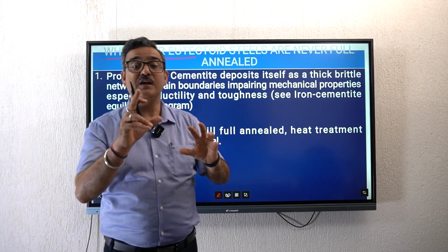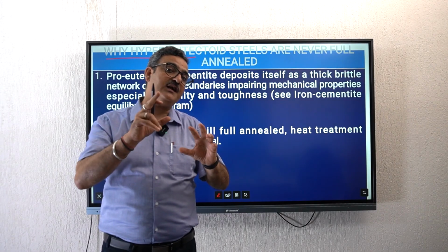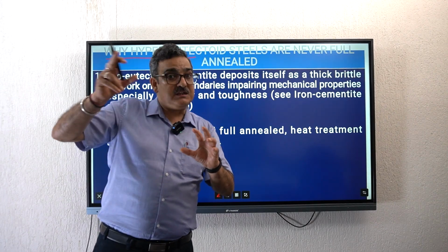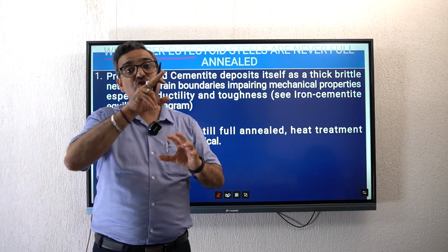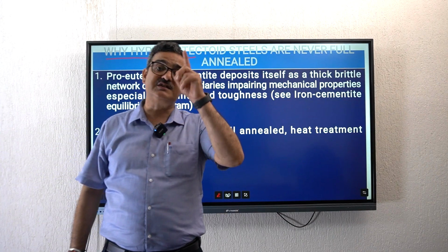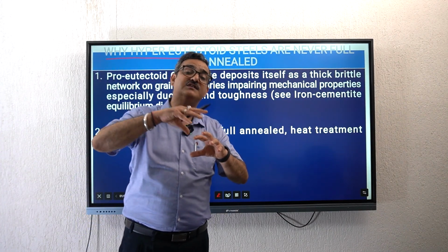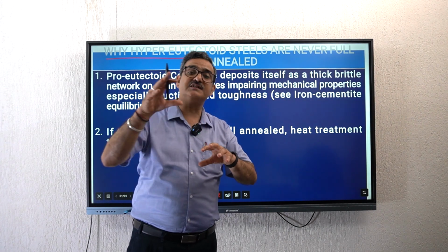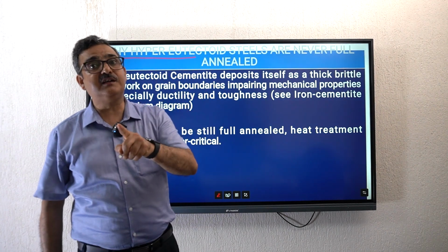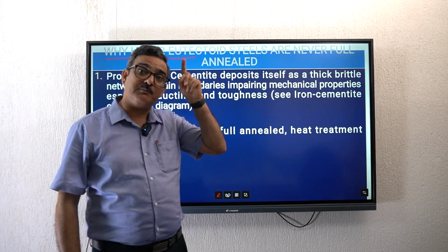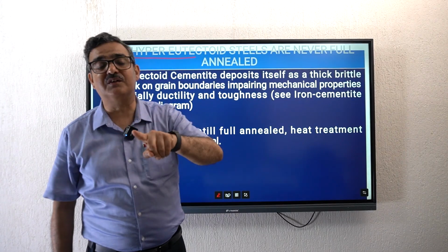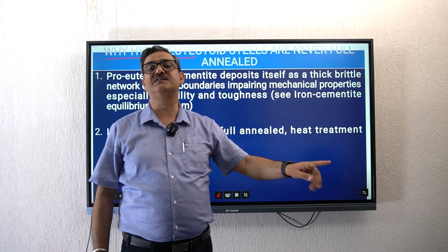But what did I tell you? If pro-eutectoid cementite happens to precipitate in any steel under slow cooling conditions, which is the case during full annealing, they'll always come at the defect areas, grain boundaries or other vacancies, etc. And they will come at the grain boundaries in the form of a very brittle network which will impair the mechanical properties of the resulting steel.